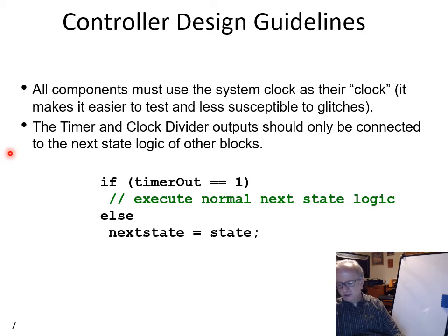And given the hazard of hold times, well, setup time violations are bad, but there are workarounds for them. But if it results in hold time violations, your chip is really useless, or at least useless for the situation that causes this to occur.